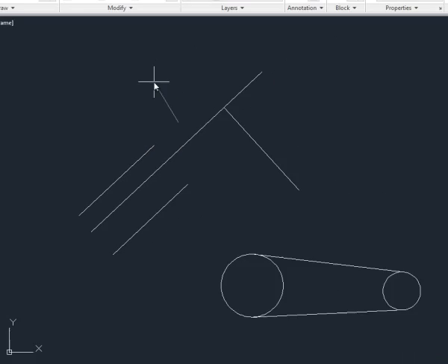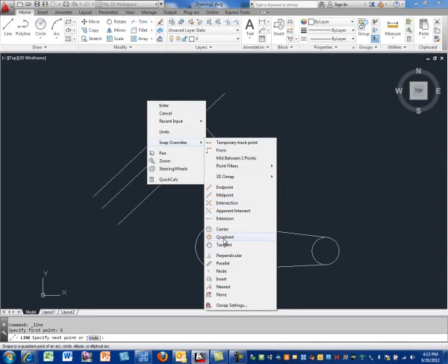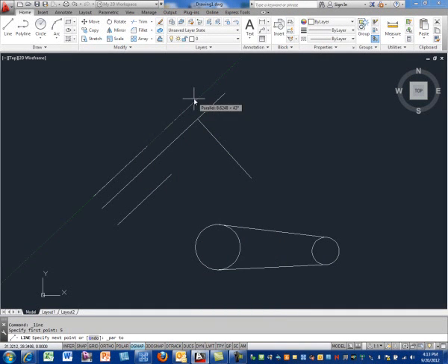And maybe I want to be parallel to that, so I will right click and go parallel again to draw parallel to the existing line. And maybe I want it to be 15 units again. So that was extension. Let me try this again. I'm going to go to the line command, hover over the end of a line, move away, get my tracking line. I'll go 5, enter. That gives me another point, and I'm going to snap perpendicular to this line that's in front. So that's extension. If you want to start a point out in space a certain distance off the end of a line, that's using the extension Object Snap feature.